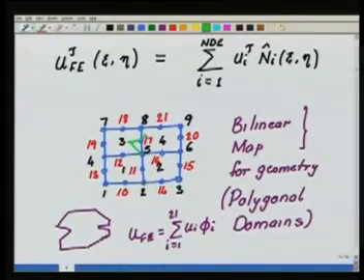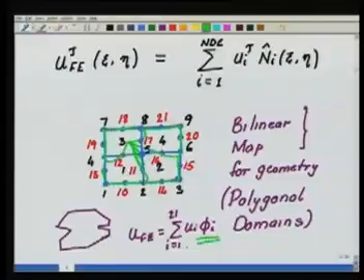So if I look at the fifth phi, it will be 1 here, it will die off like this in this element, and then it becomes 0 on these edges. In this element it will have this kind of behavior, and then it will vanish here, here, and here. So this phi is like this kind of a tent. Similarly, by piecing together these element shape functions, we can have the global phi definition, which we have discussed many times over, so there is no ambiguity.